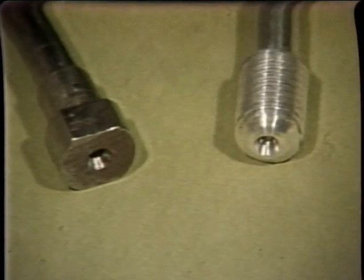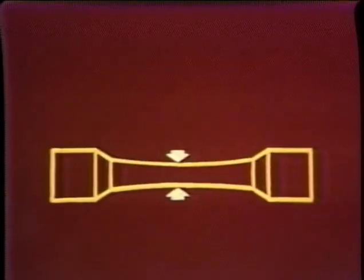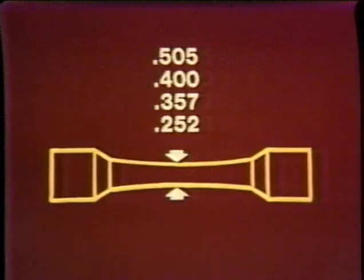Published codes provide requirements regarding preparation of the specimens which must be considered. The reduced section of the specimen is usually tapered about 5/1000 inch from the ends to the center. This allows the fracture to occur approximately in the center where the specimen is thinnest. The diameter at the center will vary depending on material thickness and code requirements.